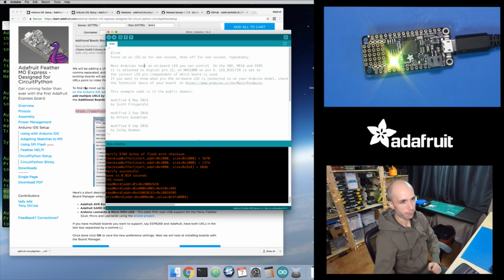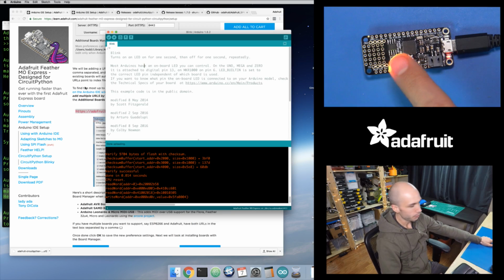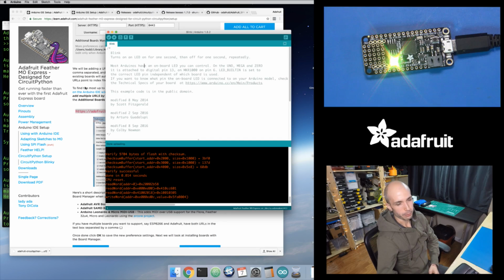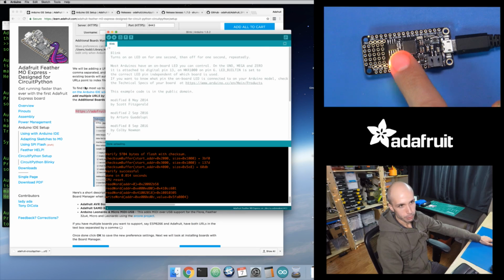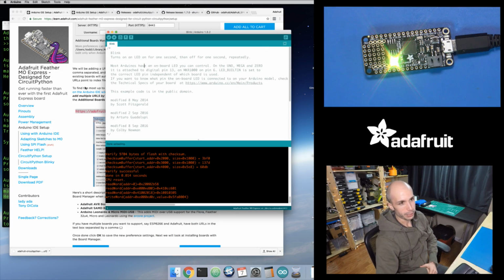So you can open a file and write to it and read from it, or you can list all the files in a directory using this SD card library. So I took that SD card library interface, the exact same functions and objects, and just plugged in an implementation that talks to our 2 megabyte flash chip right here. So you can store files, read files, write files, create directories, delete directories, pretty much anything you can do with your computer file system on this 2 megabyte flash chip from Arduino, which is pretty cool.